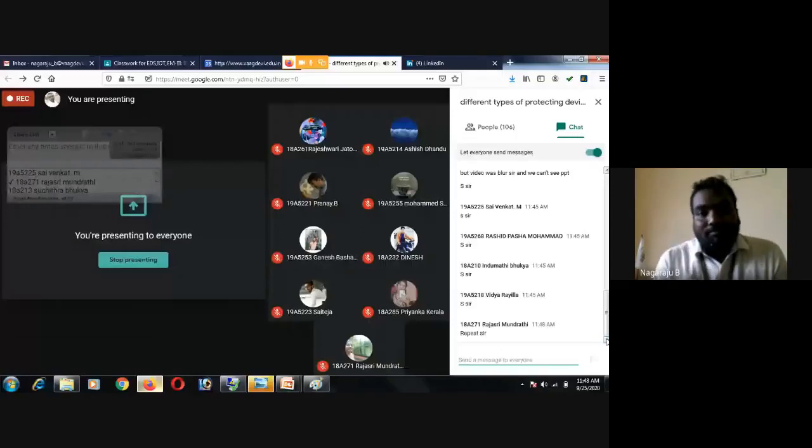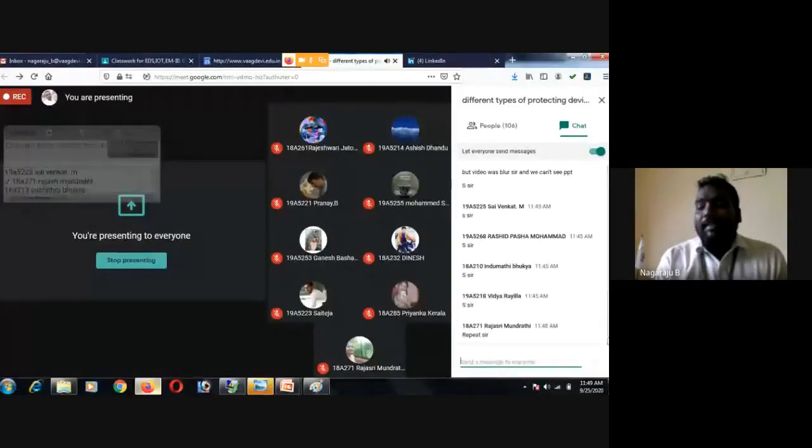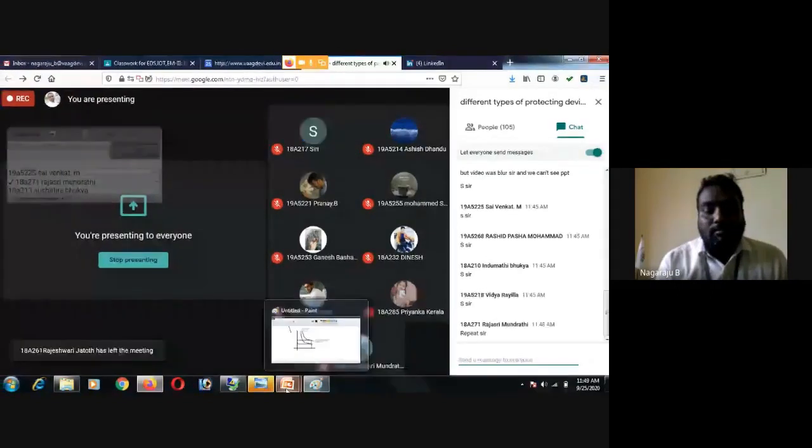Tell me, fuse is a one conductor. Okay, fuse is an overcurrent protecting device, which has a withstand capacity, and a circuit opening fusible member, directly heated, and destroyed by the passage of overcurrent through it, in the event of overload or short circuit.